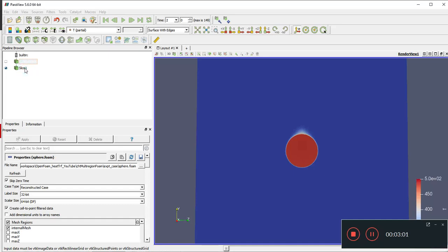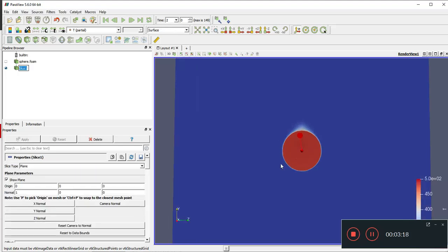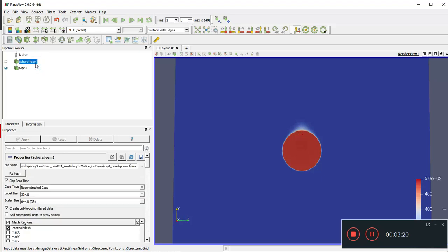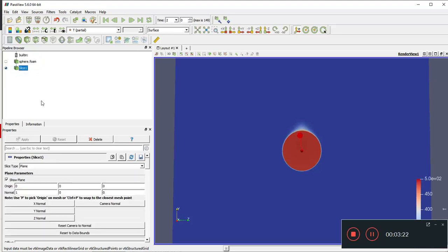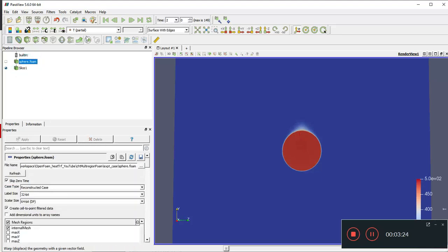You can see that the sphere is pretty hot, and already you see the boundary layer forming and there is convection happening, which means the fluid is a lot less viscous than before. It is a good result because the boundary layer is pretty thin and there is some flow there, which is very good.